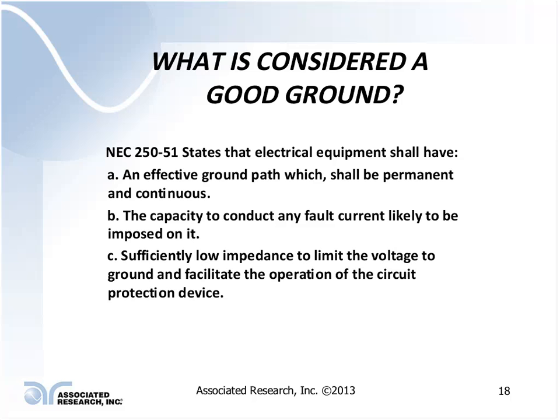Basically, it says that the ground circuit really shouldn't act like a fuse. It should be able to handle any fault current that is likely to be imposed upon it itself, and it's got to keep the voltage low enough so if I'm holding on to that product when a fault occurs, I shouldn't receive a shock due to the voltage that's being induced onto the enclosure of that product.